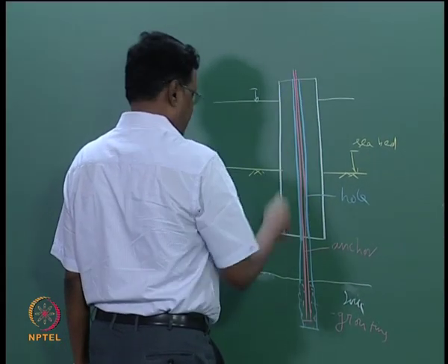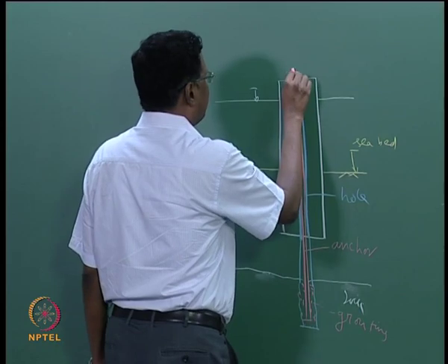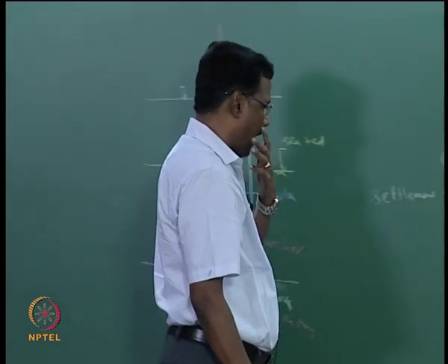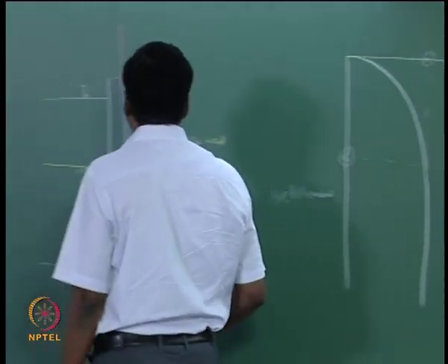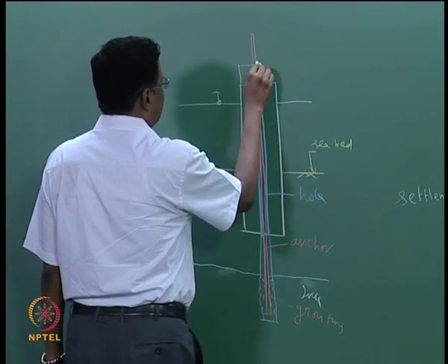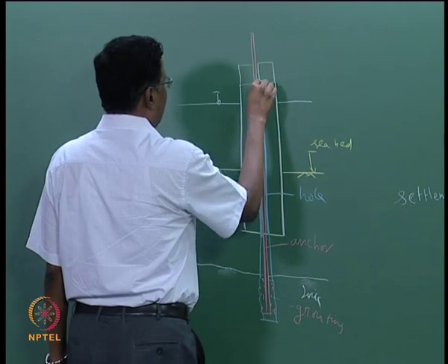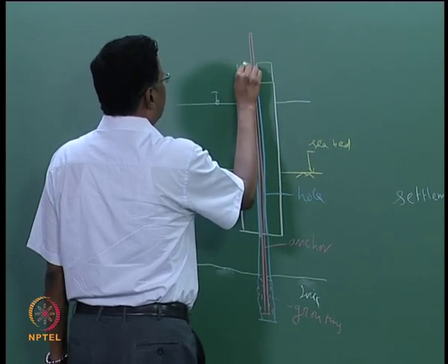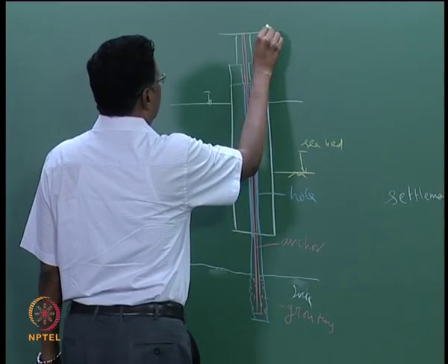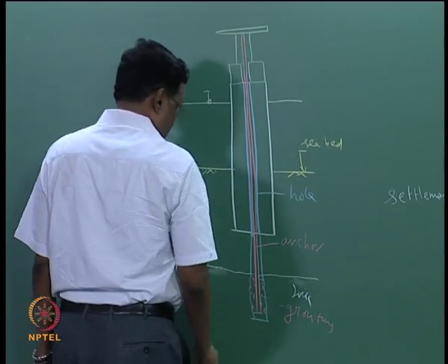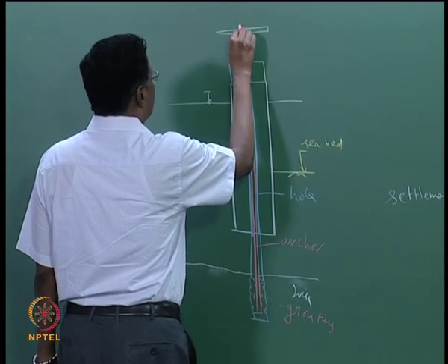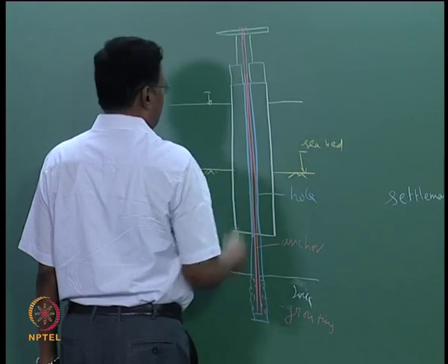So here we will place one jack, which will be a hollow jack, it will have an opening here through which you can take the anchor, and we will have the piston going there, the piston also will have a hole, and we will have the plate. So this anchor will be connected to the plate like this, with a bolt and nut arrangement.